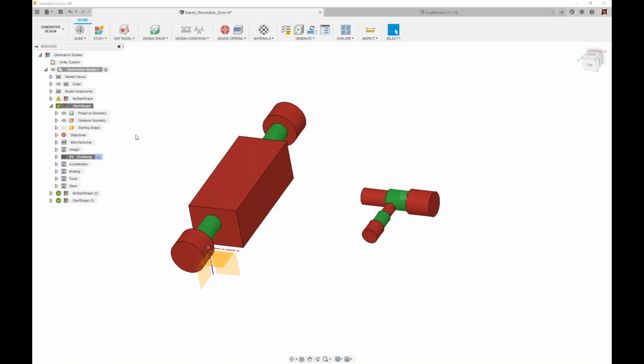Okay. I don't have anything else to add there, but I can comment on these next two. Can we say topology optimization is maybe a subset of generative design? Perhaps yes, you could think of it that way. While topology optimization is trying to get you a single solution for a setup, generative design is almost doing a design of experiment across topology optimizations for you, right?